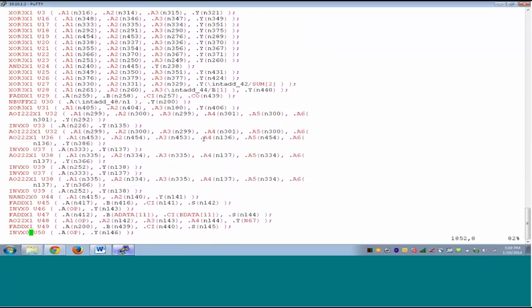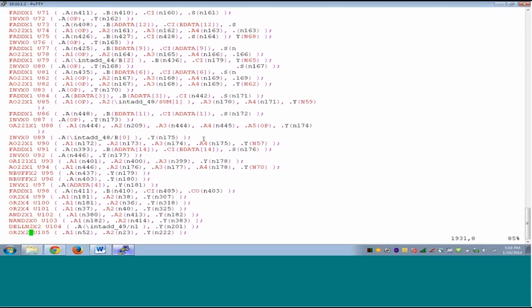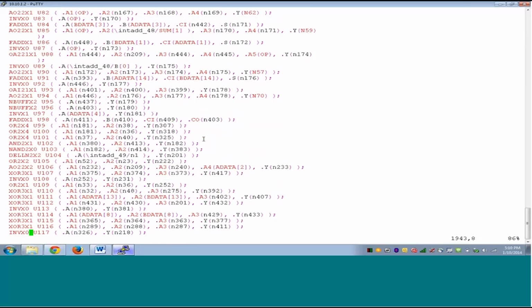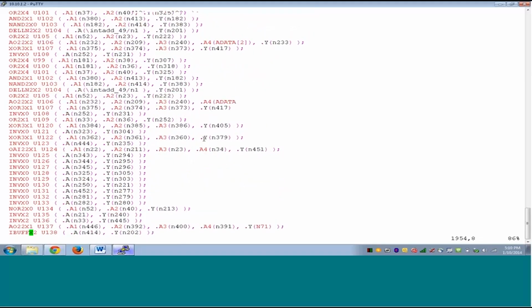Why? Because by default, during compile, Design Compiler will ungroup. It will ungroup DesignWare components. You cannot see the actual architecture of DesignWare because it's proprietary. You only have the information of what it does and how you should code it. In the compile process it will also ungroup the hierarchy, and you are left with all the registers or the combinational logic.